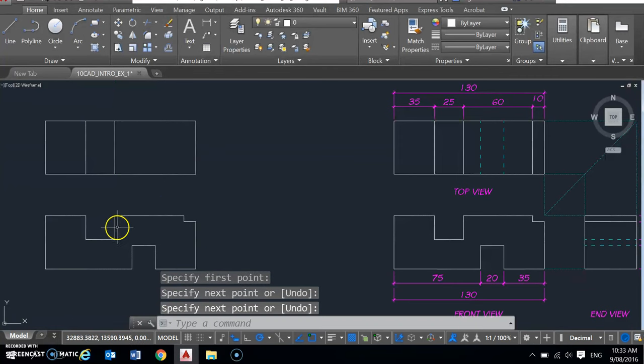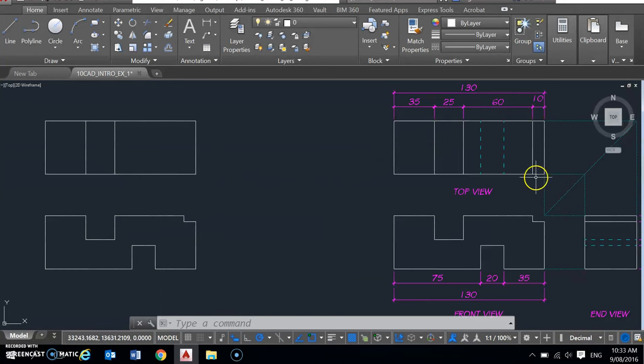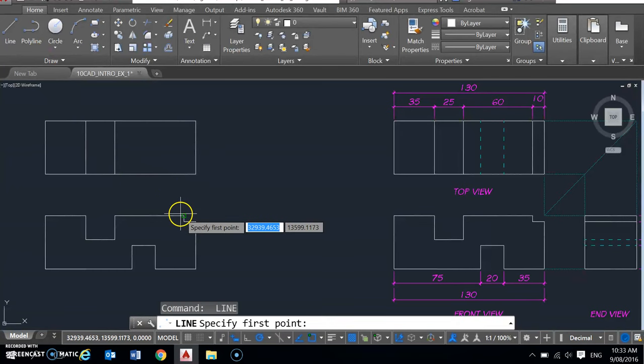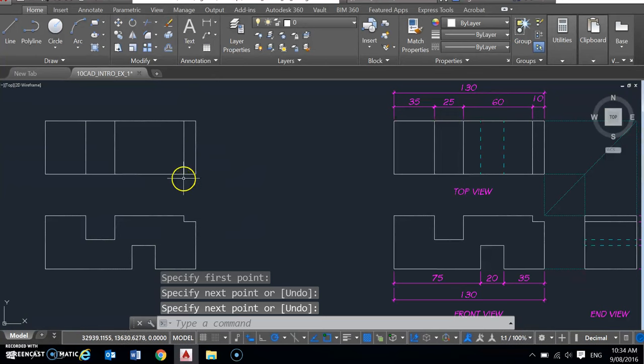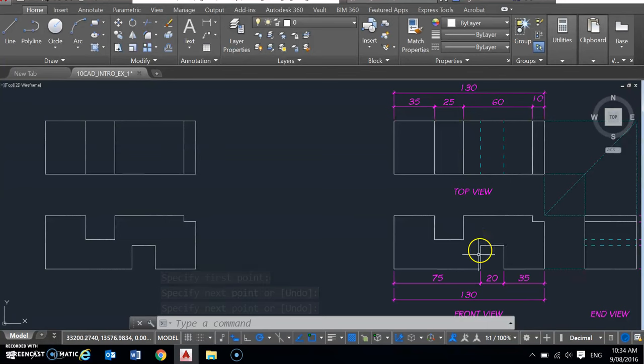and there I have these two marks indicating this groove. I want to put the rebate in the top corner, so again I'm going to press the space bar to repeat the command. Hover over the end point and drag up, left click to start the line, left click to end the line. And now I've got nearly all that information. The only bit that's missing is this hidden detail showing the groove in the bottom, this bit here.